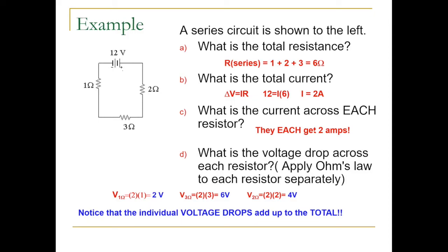So as long as you understand that the current is the same in a series circuit, how to find the total resistance, and how to find these individual voltage drops on the devices, then a series circuit should be a straightforward circuit for you.